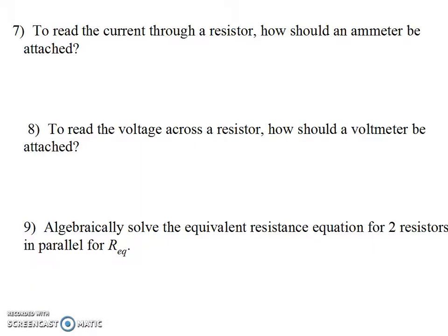Okay, so by putting all the circuits together, we should have been really good at this. Ammeters are connected in series. Since ammeters measure current, you want all the charges that will either eventually go through the resistor or have already gone through the resistor to go through the ammeter. So it's got to count them all up. It's got to be in series, one after the other.